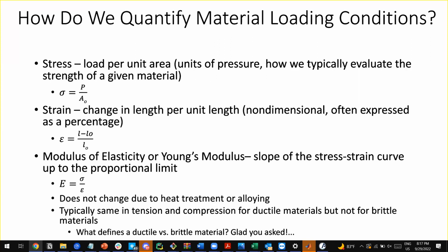So Young's modulus is really important in characterizing the stiffness of your parts. It is an intrinsic property of the material, but it can really affect the stiffness on a bulk level once you design the part. For example, if I have a shaft and I'm trying to characterize its displacement under a load, the higher the Young's modulus, or the stiffness, the less it's going to deflect per that load. So it's important to understand the relationship between stress, strain, and modulus of elasticity. Those are pretty much the three core principles of solids.